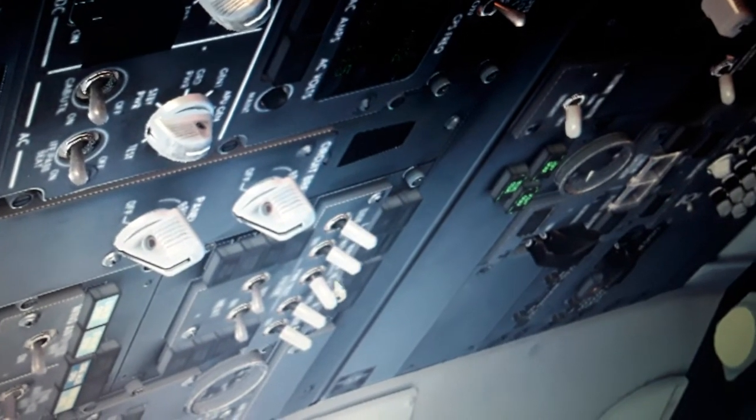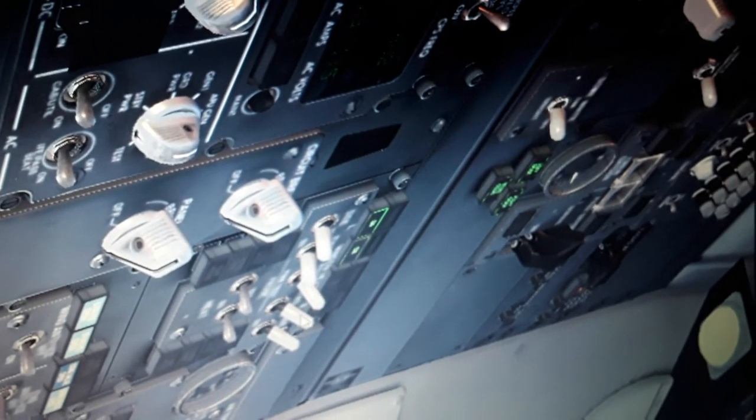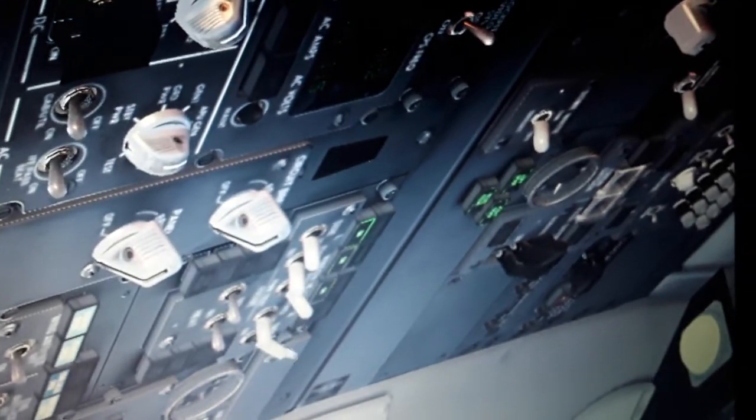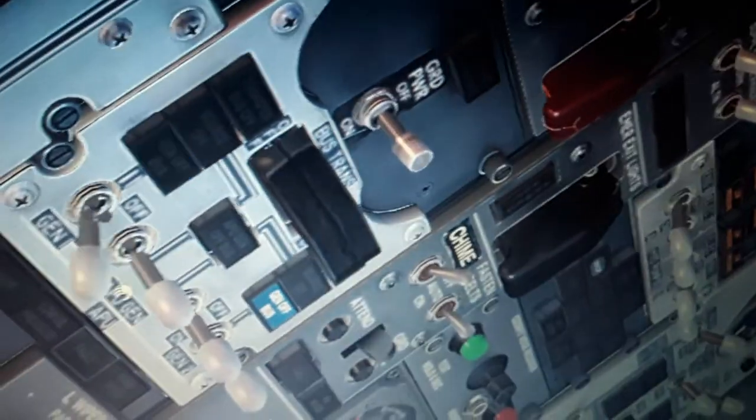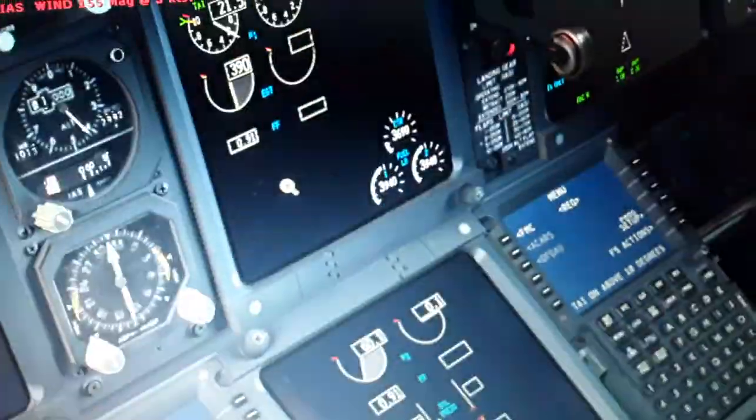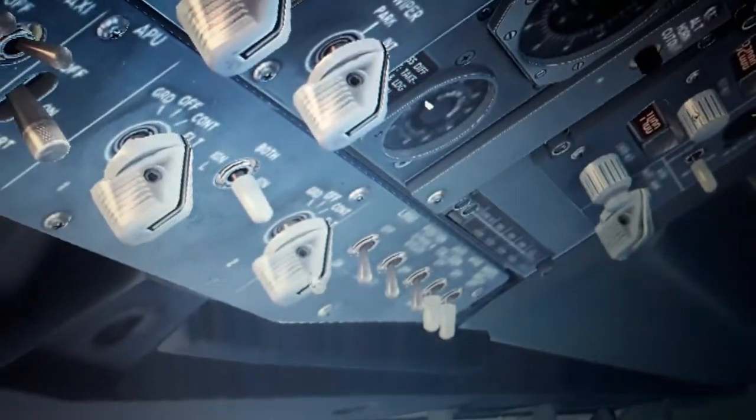We can use this window heat on again now. We have electrical now. We can connect the engine, the left engine. Here we have a lot of electrical. Then we can turn on this switch, leave it in this position. So now we start the right wing engine. This wing engine, we go in this mode, ground. So we're gonna have the right wing engine now.